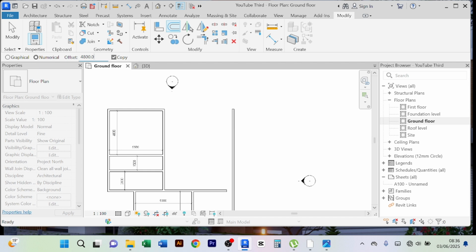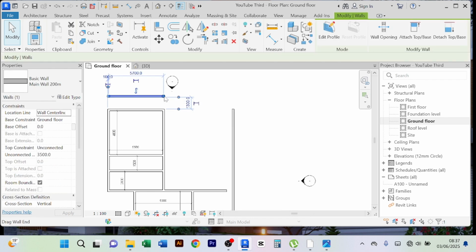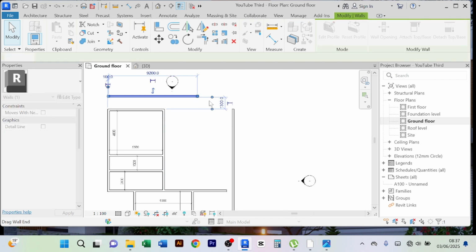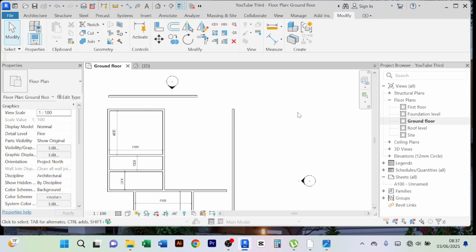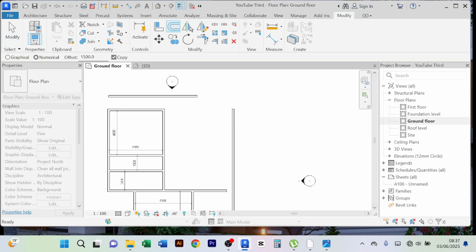I'm going to offset it by, I guess, just 2 meters, a little bit, not even 2. I can say 1.5 probably there, 1.5 outside. Of course, this is going to extend a little bit here. Then inside, I'll offset it by 5. So I'll say here 5 meters.